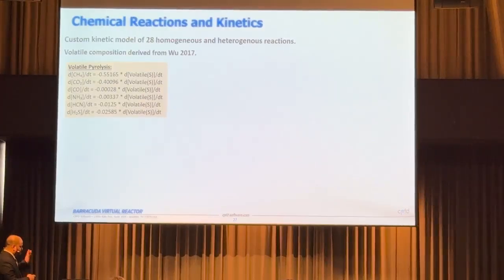Okay, I want to take a little bit of time here and explain the reactions itself, because these tend to be quite similar when you look at any sort of coal combustion or biomass or plastics. Generally, the reactions and the kinetics can vary. There can be additional reactions that can come in, but you always have certain things which repeat. The first one is a drying step, especially if there's moisture in your feed. The first step that you want to do is a moderate drying step.